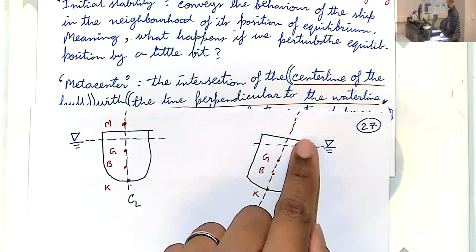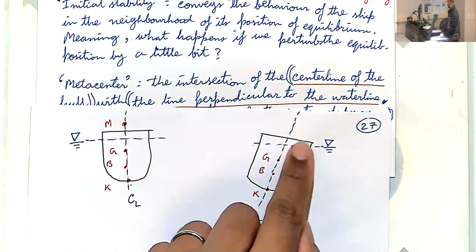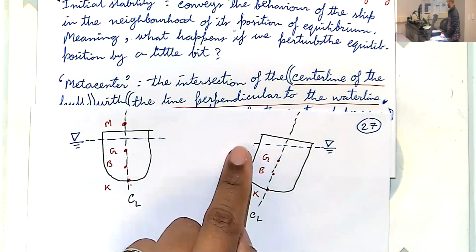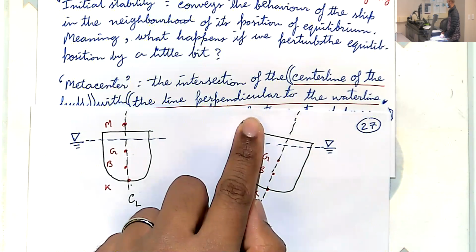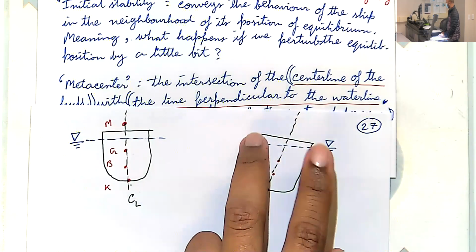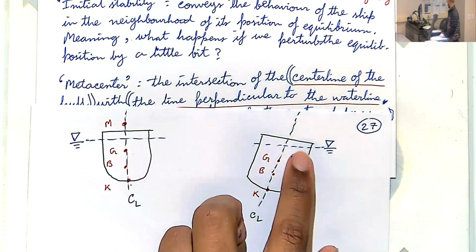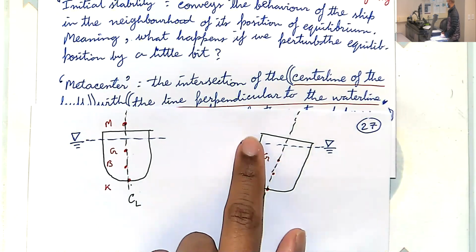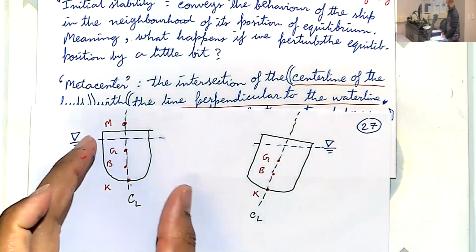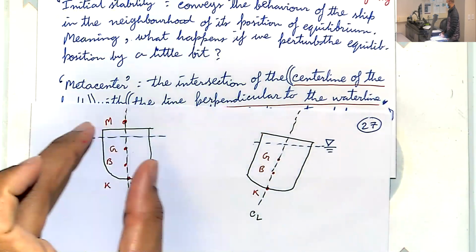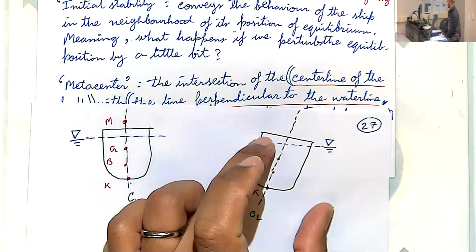So you're increasing the volume submerged on the right side, but you're decreasing the submerged volume on the left side. Overall, they're exactly equal and opposite. So the amount you submerge has to be equal to the amount that emerges. The reason is that the total volume submerged has to be the same, because the weight is the same.